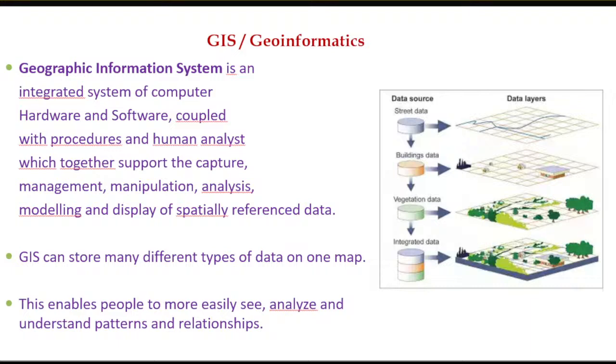So for the real-world features, we can capture the information into point, line and polygon. So this is the road. A line feature is nothing but the road feature, where you have a number of points joined together, and a point is nothing but an XY location, and here it is a polygon. The surface is segregated into a number of layers, whereas the surface is also classified as pixels, or we can call them grids.